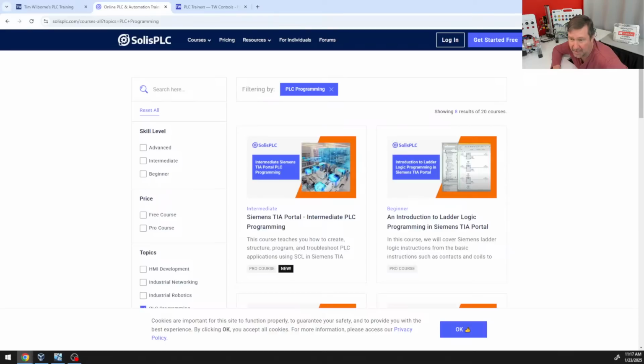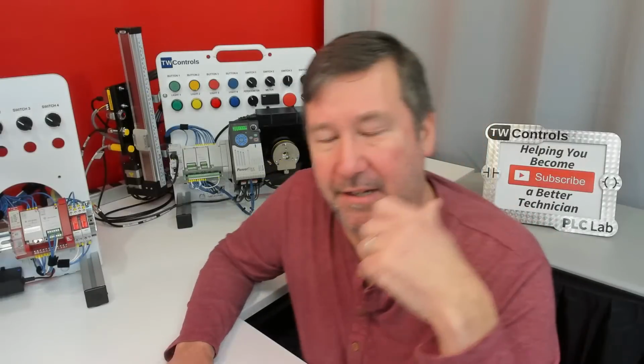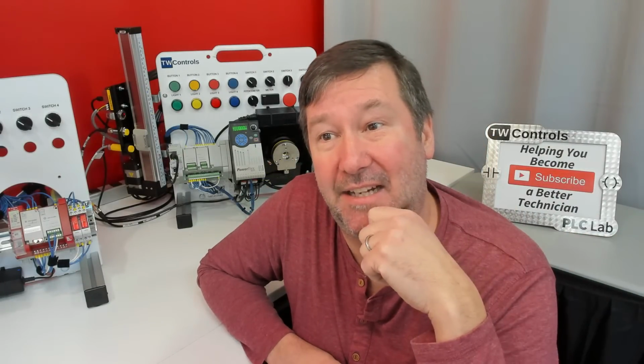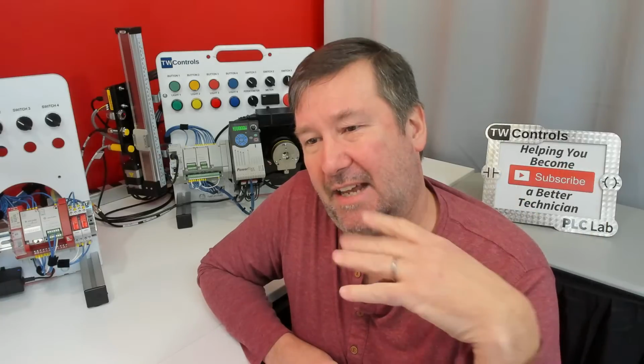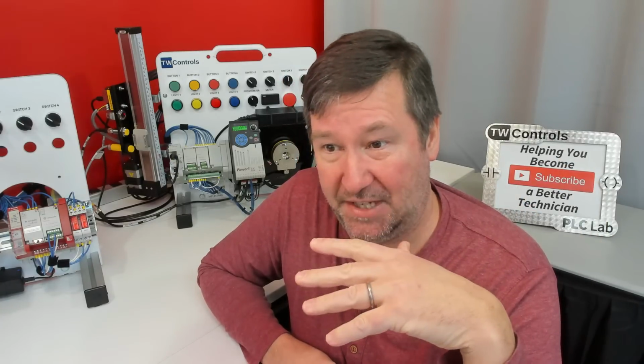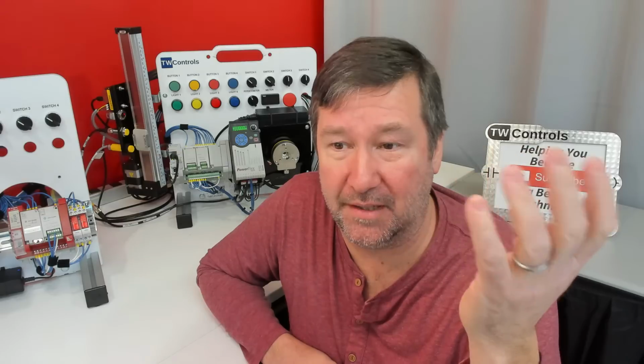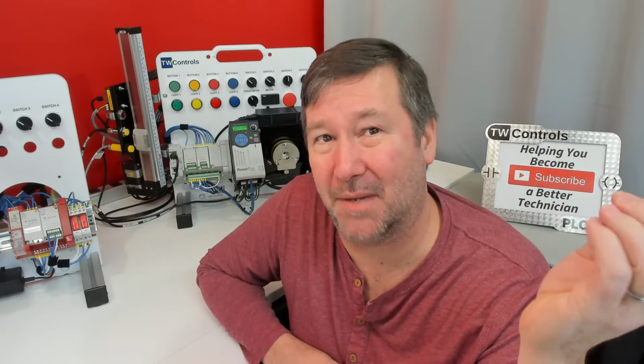Scion: benefits of using Modbus TCP to collect data from various PLCs, example, CompactLogix. So, I don't know if there's actually an advantage as much as it's a tool that we can use to get data. So, what are you trying to data log to would be the question. If it's a CompactLogix, rarely would I actually use Modbus TCP unless the particular thing I'm trying to log to doesn't support it.